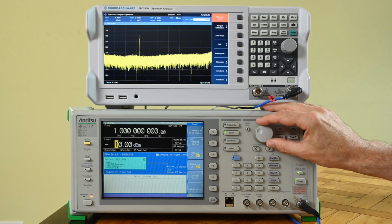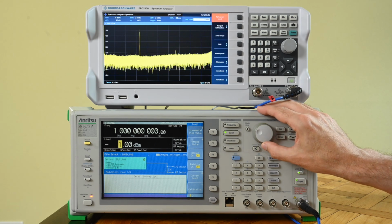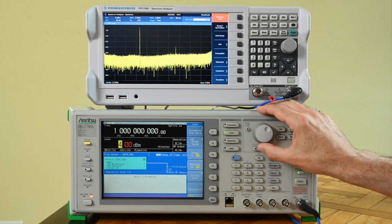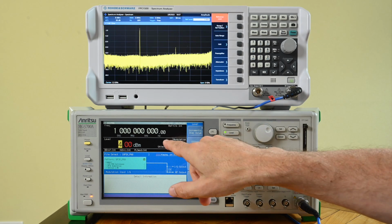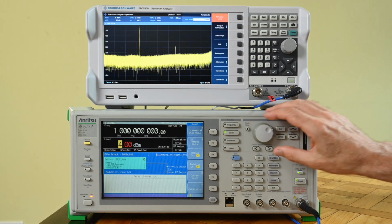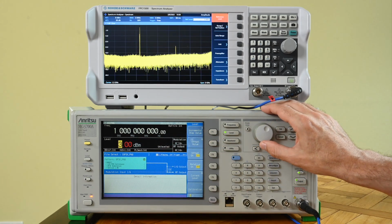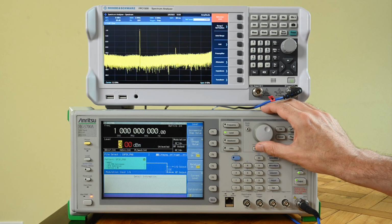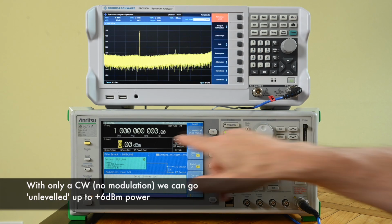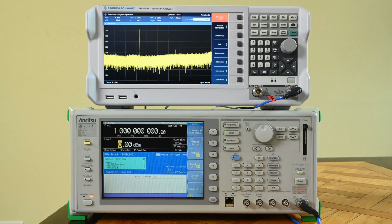By the way, in terms of level setting, as you can see happening here, if I go above a certain value, like 3 dB, then the device says unleveled. That means I'm in an over-range in which it still generates signals, but it might not be within its specifications. If we go lower than 3 dB, we operate within the specifications of the device. So this is, of course, very simple, what we had expected.